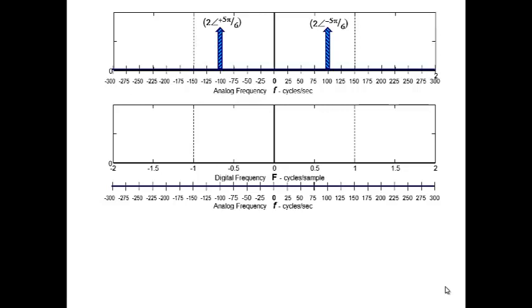Now, according to our little model of impulse sampling, we also end up scaling it by the sampling frequency, or 1 over Ts. So what we get is a scaled version of that original one. It was scaled by 1 over Ts, or in this case, multiplied by fs. Hasn't changed the angle, just changes the magnitude.